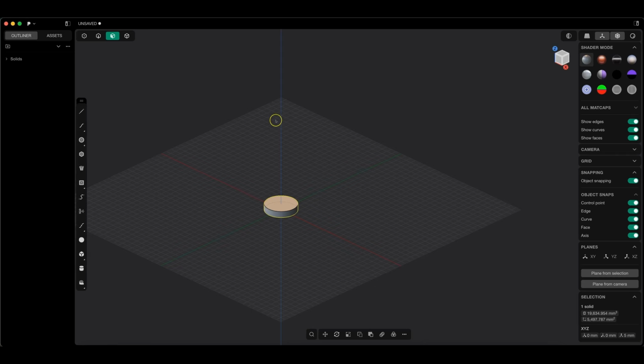And now we have a cylinder created, and next we'll create a path along which we'll sweep another profile. We select the line drawing command. We place the starting point of the line at this point. Here we have these handles that make it easier, and we drag the line along the z-axis, press the tab key and enter 70. Now, to avoid finishing the line drawing because I want to create a second segment of this line, I simply click somewhere with the left mouse button to place the line on the z-axis. Just click the left mouse button on the z-axis.